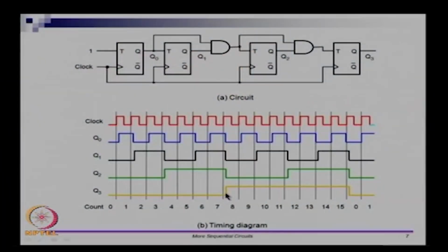So, this is a concern, but this circuit is called a synchronous circuit. There are several ways in which you can cut down on the delay. You do not have to wait for n minus 1 AND gates delay, you can do better things than that, but as of now you can see that all the outputs are actually just clock to Q delay. Each of the bits is only a clock to Q delay away from the clock. The delays from the clock are not adding up.